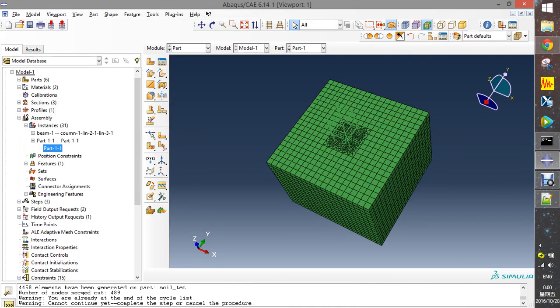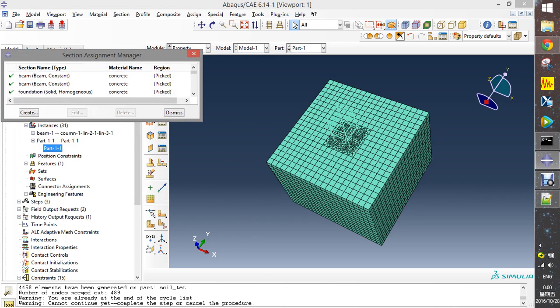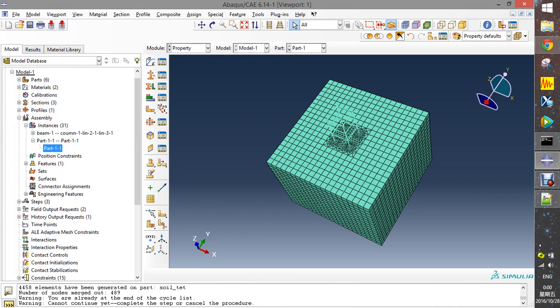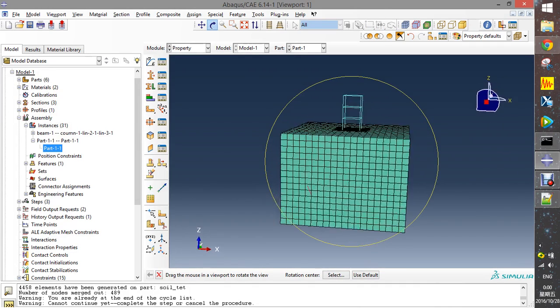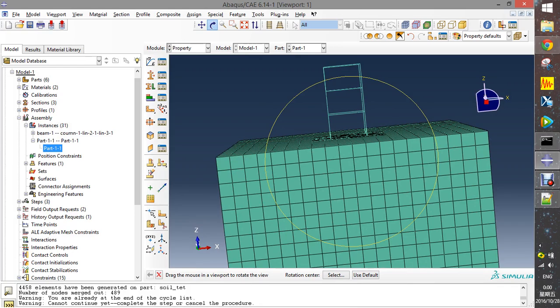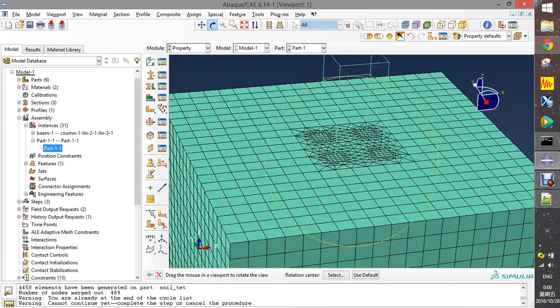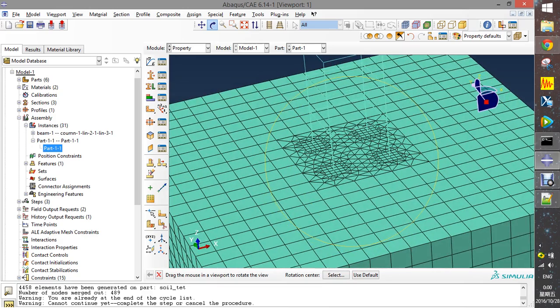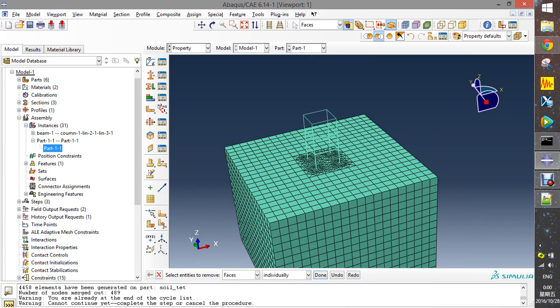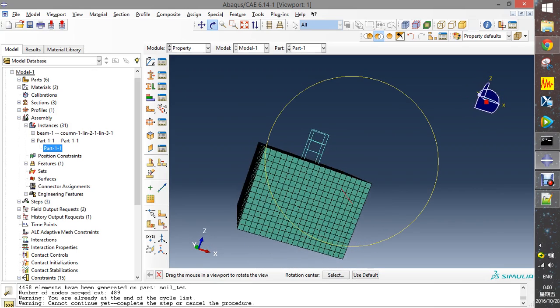We check everything, the part, properties, soil, sections are assigned, and oh, I forgot, because we created another new part, so all the sections here, we need the beam orientation, we need to reassign. Yes. First we did say remove all the useless elements.